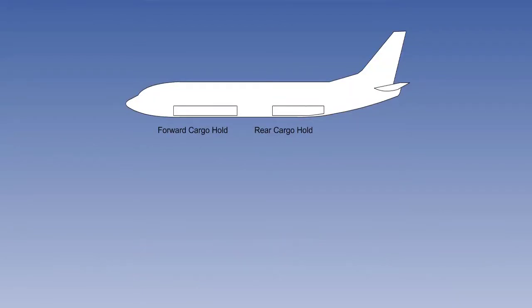Baggage and cargo are usually accommodated in compartments, commonly known as holds, in the pressurized area of the aeroplane under the main cabin floor. The compartments are heated and feature fire-resistant side walls, ceiling and walkways, smoke detection and fire protection. Cargo compartments usually have a maximum floor loading limit, mass per unit area. For example, kilograms per square meter, to protect the floor against structural damage.